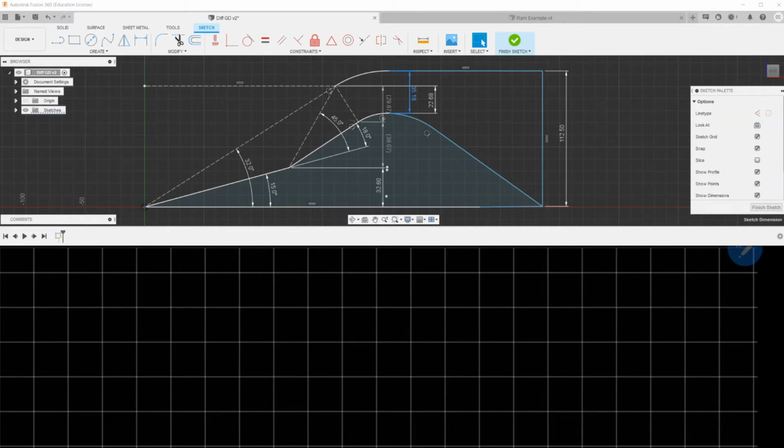The diffuser must sustain the drag when this structure accelerates from subsonic to supersonic velocity. In our case, we already assume that this acceleration happened and we are flying with a constant but supersonic velocity. So in our case, the wave drag is the drag caused by the presence of the number of shock waves in our structure. And this question was explained in the book. Here briefly I will repeat the main idea of how it can be calculated.